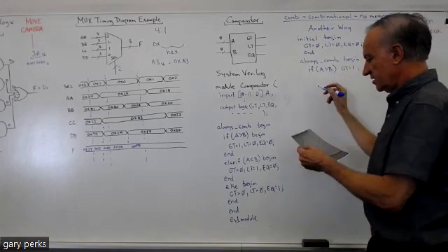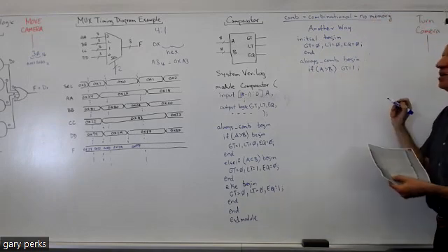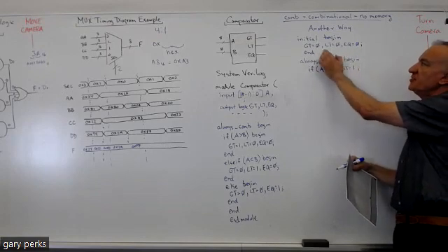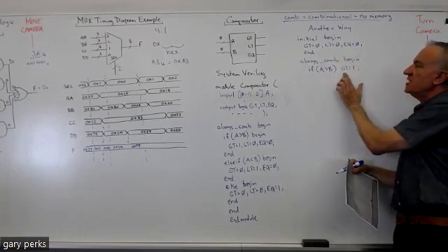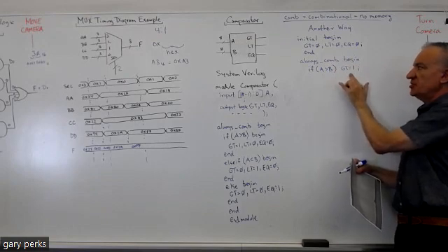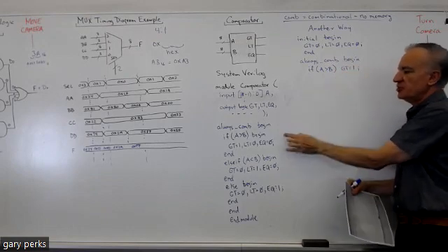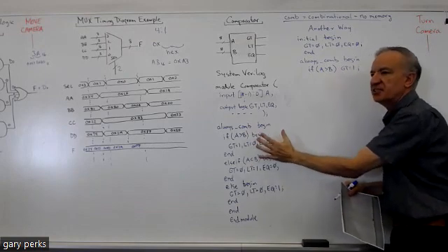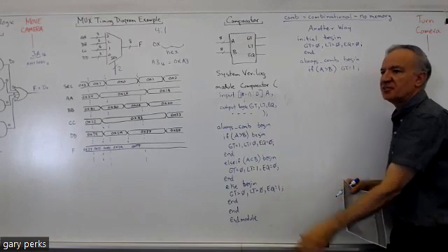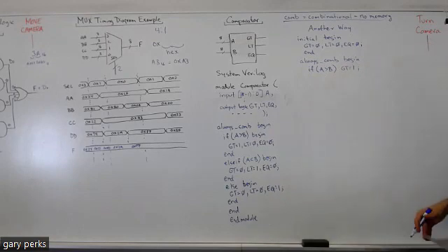Would you need a begin? You said no, right? Yeah, that's the key thing. If you initialize your values first, within the if you only have to put the output that changes. Because it's a single output, you don't need this begin end like you did here. That's why some people like this. It saves you some typing, especially if you've got a lot of outputs.